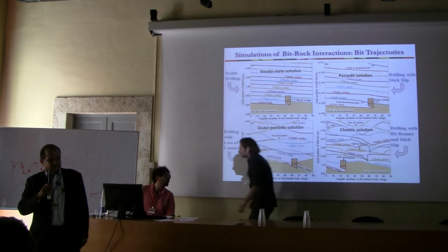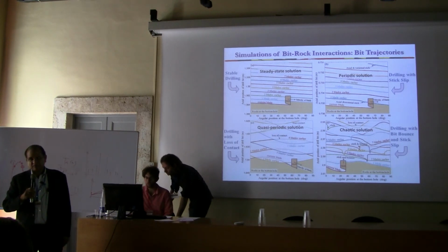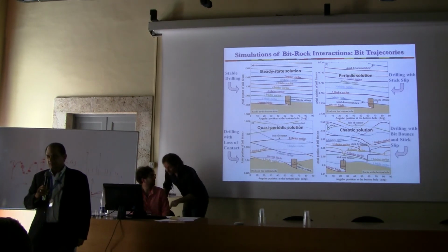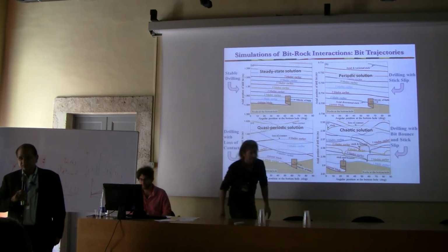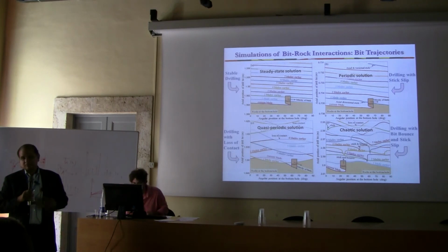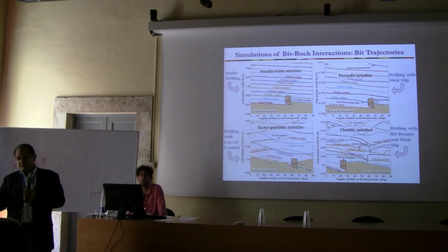If I may, there's another thing for which the companies are very protective of data. If you want to do decoupled analysis and you deal with the forces on the drill bit as imposed kinematics, then it would be very nice to have information about the spectrum of the moment and the forces which are applied there. And clearly you have two drill bits. One is a polycrystalline, the other is the tricone, where the spectra of the forces and the moment are different. It would be very nice if everybody was doing it.